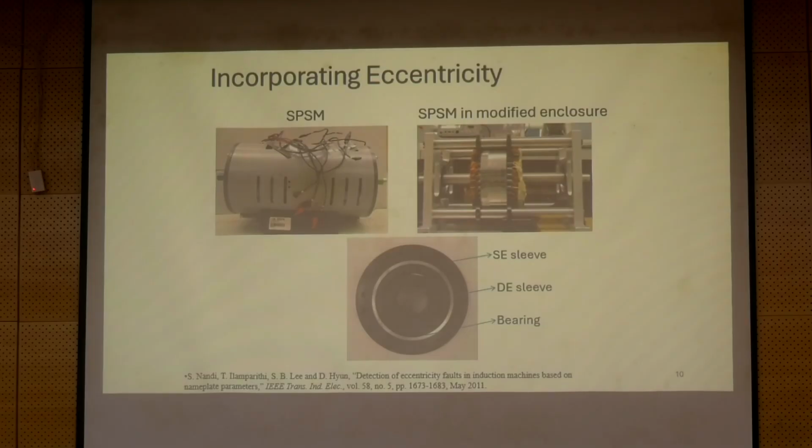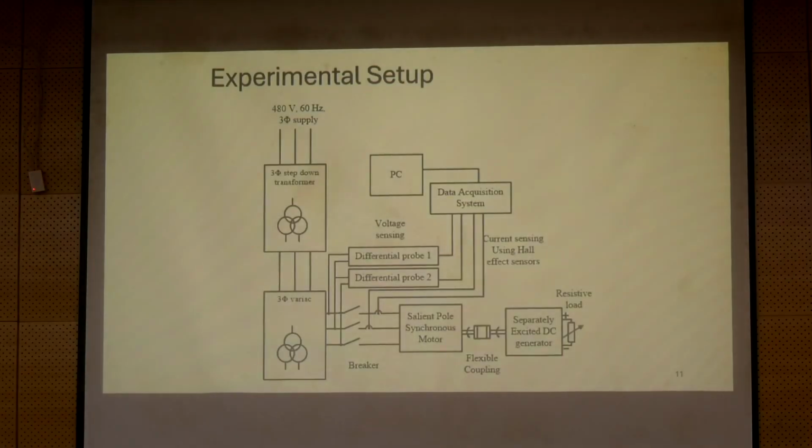So is this okay? So this is the setup. Whenever I say I collected data, a setup like this is what I used, and this is how I collected data. So there can be many sources of noise in this setup, or even error when we collect data. For example, the probe setting, the attenuation factors might be noted incorrectly. Or the Hall effect sensors, the clamp-on type sensors.